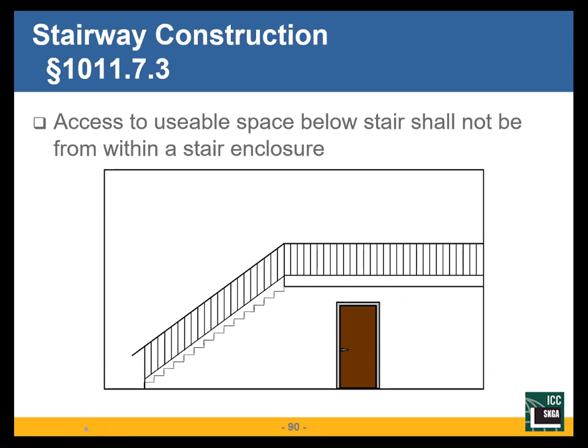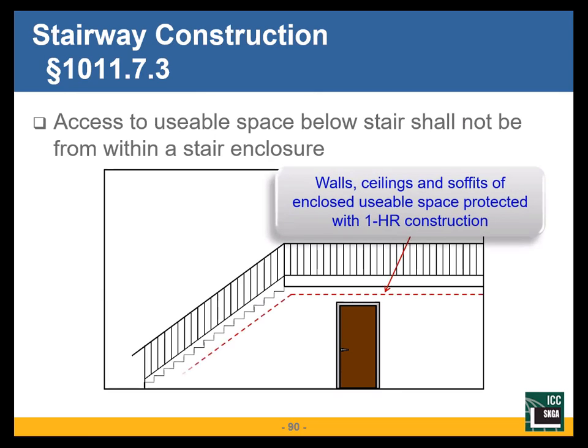The stairway construction. Can I have storage underneath my stairs? Can I put storage underneath the stairs? You can if you separate that storage with 1 hour construction.